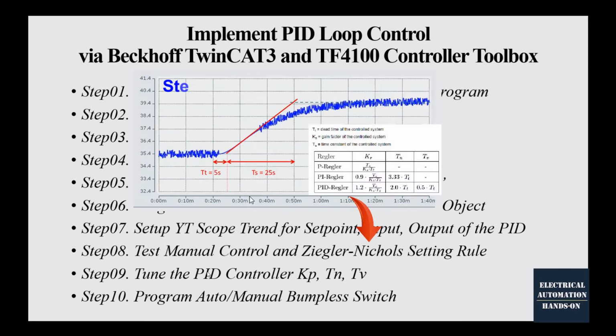So that's why for the Ziegler Nichols method today, I would like to introduce the one commonly used method. Usually we call that the first method of the Ziegler Nichols method. The basic idea is we give the output a step response, record the system step response, and record 2 times within the trend. Using these 2 times, we can basically calculate the PID 3 parameters.